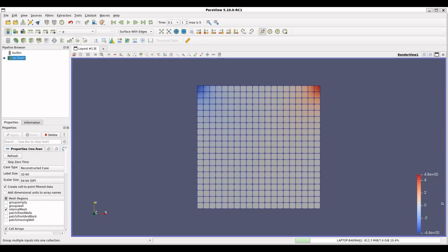Well, I'm confused. He is talking about post processing. How do you go to steady state? In steady state, there is a time dependent problem. Time is given, 5 minutes, 5 seconds. Yeah. But the steady state condition. Yeah, you just go to the last time step. That's it. And if you make sure that you have reached that fully developed state of the flow, you don't need all the previous stages of the transient. You just need one snapshot. You don't need animation for steady state, unless you want to see how the transient phenomenon occurs.